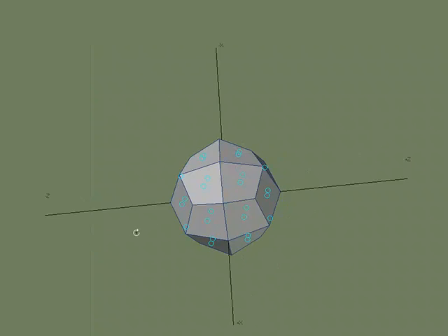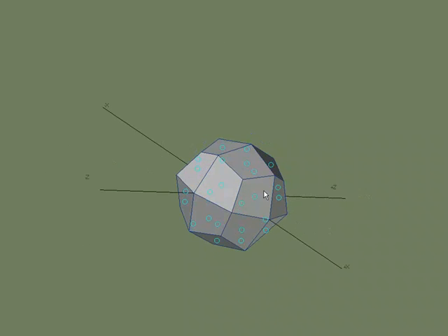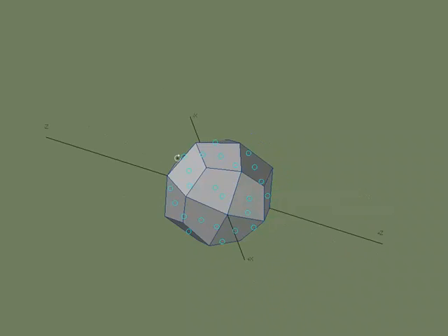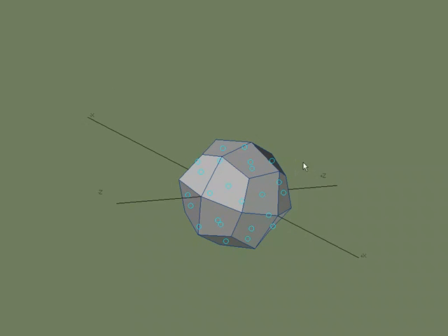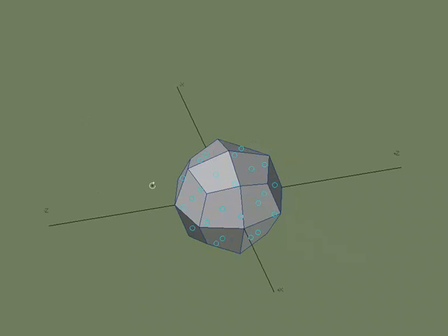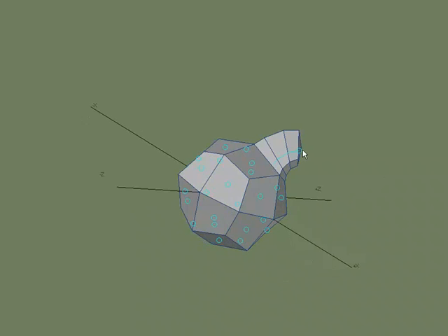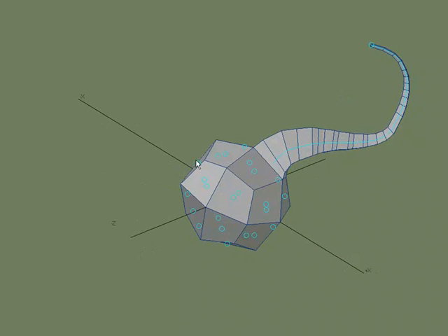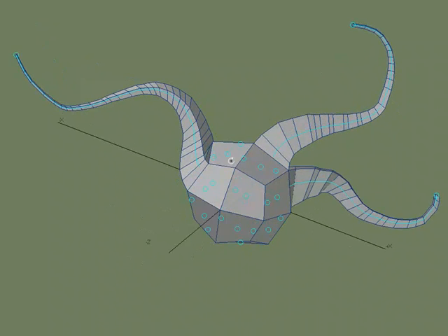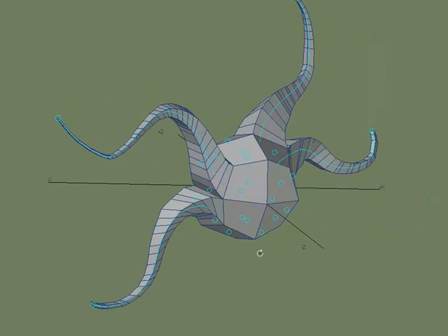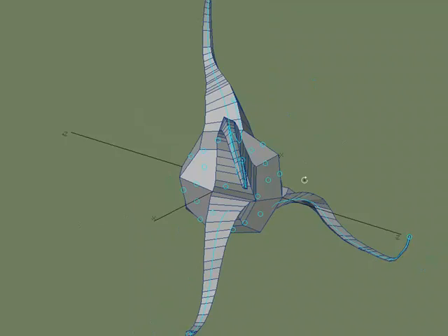And when you activate Magic Bevel, you get a handle. This little blue circle is a handle. You get a little handle for each polygon that you have selected. And since I had nothing selected, everything is selected. And I can just left click and drag. And I'm performing multiple bevels just by left clicking and dragging. And I can just pull that out, just like so.